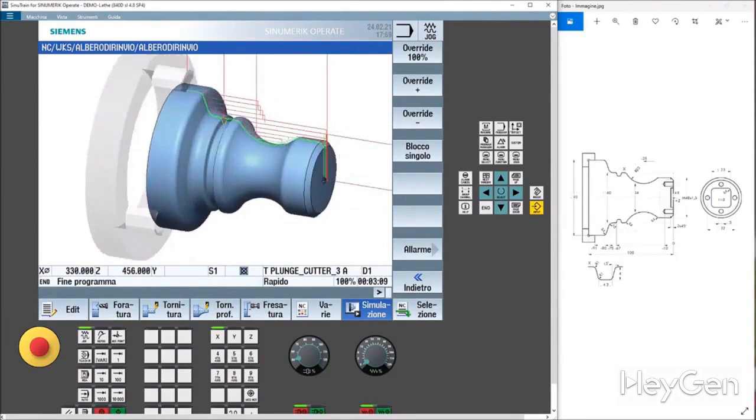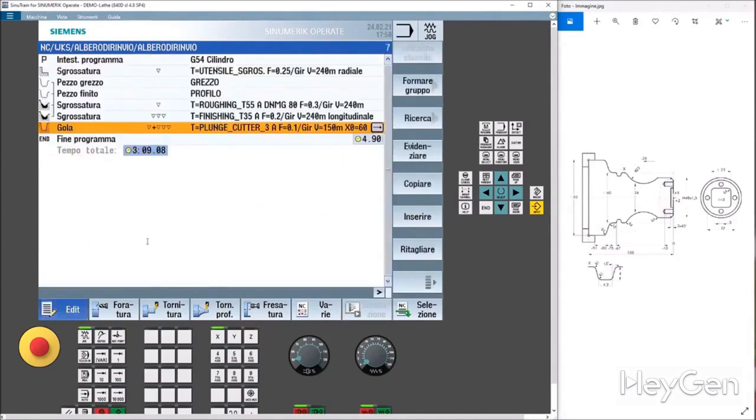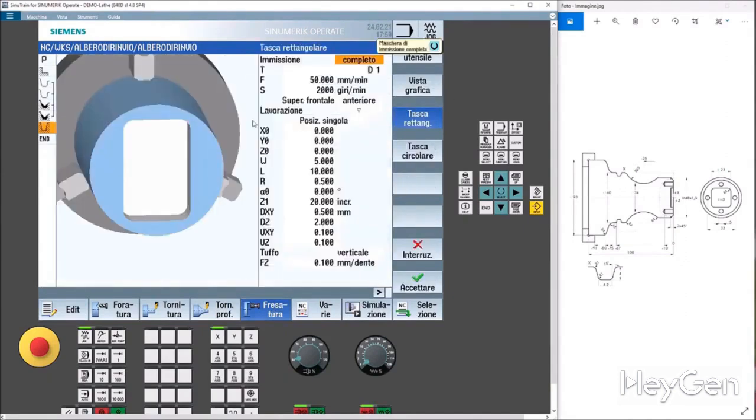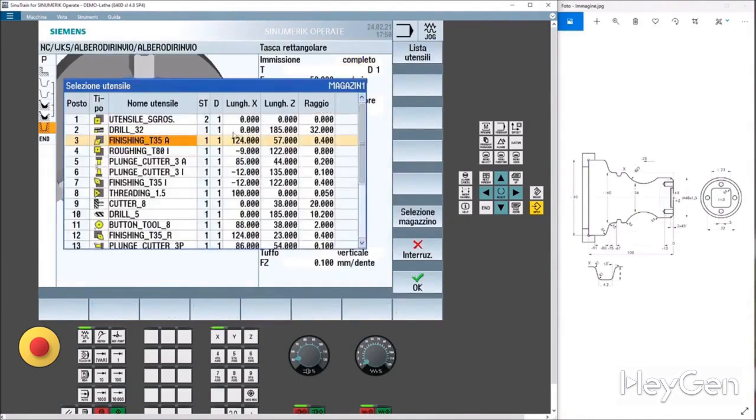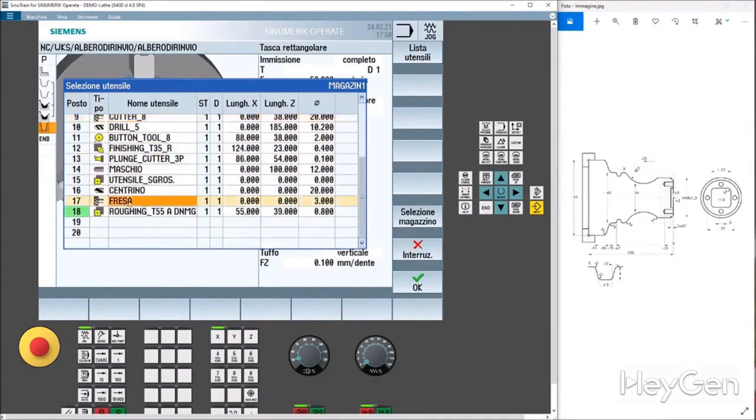Now let us start working with some of our powered tools. So, let us go back to our milling program once again. I really want to mill a very nice pocket. Here it is, a nice square pocket. Select tool, check cutters. Diameter 20 is too big, 3 is small. Need diameter 8, 20 is a bit excessive. Here it is, let's use this cutter. Diameter 3, a bit small. So we need radius 4, so diameter 8.